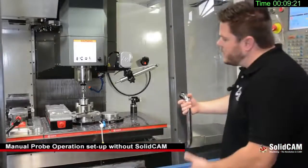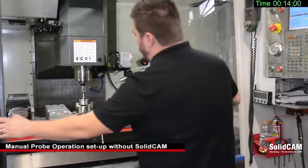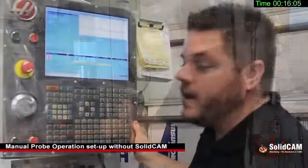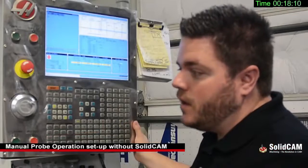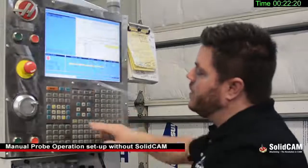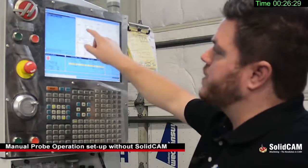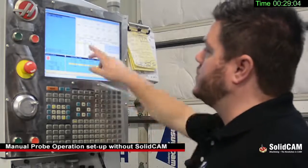So once I found approximately the center of the part and I get to the depth that I want, I'm going to go ahead and close the doors. Now after we have the probe aligned inside of our bore, I'm going to come up here into the G54, and we're going to make sure that we select the tool path that we want for the probe. In this case, it's going to be 1, which is bore.